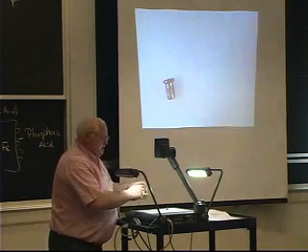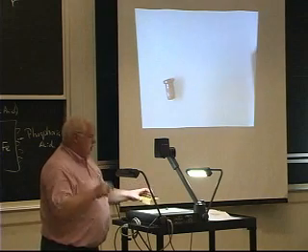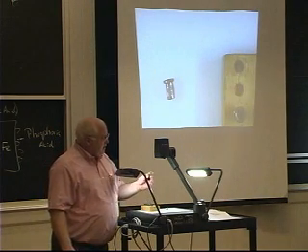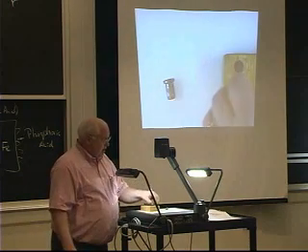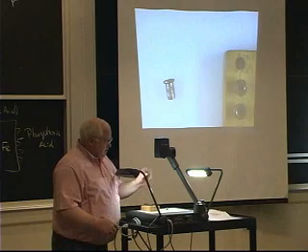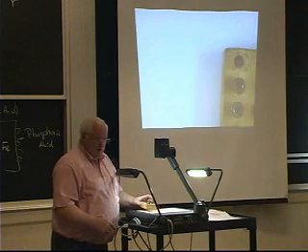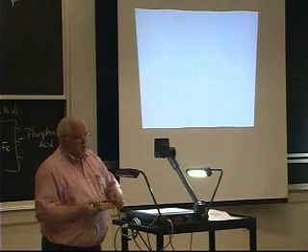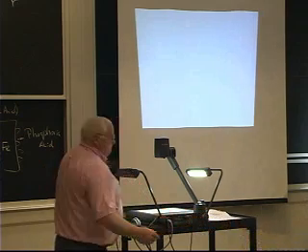If you look inside, this is the only waste inside there. It's a little plug, a little steel plug. They punch out in the next operation. The next one, what have they done? Oh, they made a counter bore here by extrusion. Then they put the knurling on. Then they did the internal threads in the threading machine, and then they zinc plated it. And that's all the steps in making that little 2-cent part, or whatever it costs, okay? So you can pass that around.